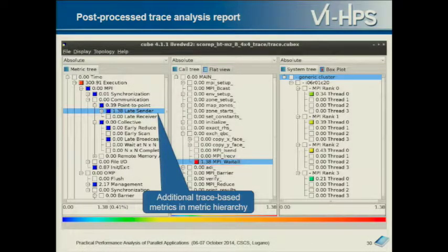So it will show up as underload on some of those processes. The time on the processes above the average matches the time on the processes below the average. In this case, process 6 had exactly the average time. It is not overloaded and not underloaded. It would not be changed by balancing here.